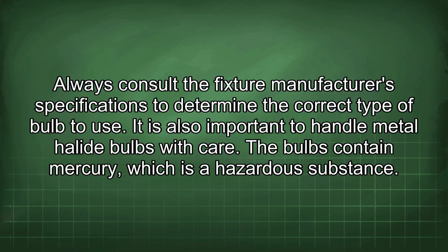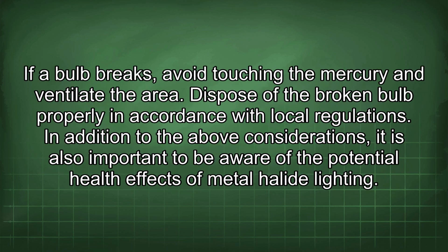It is also important to handle metal halide bulbs with care. The bulbs contain mercury, which is a hazardous substance. If a bulb breaks, avoid touching the mercury and ventilate the area. Dispose of the broken bulb properly in accordance with local regulations.